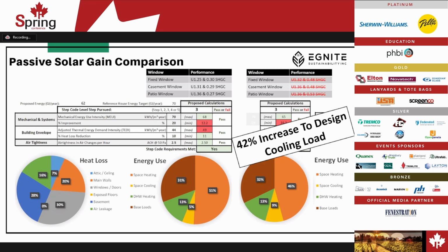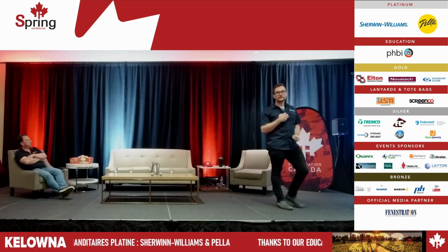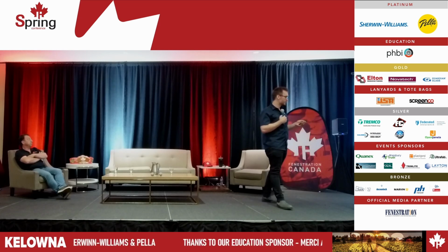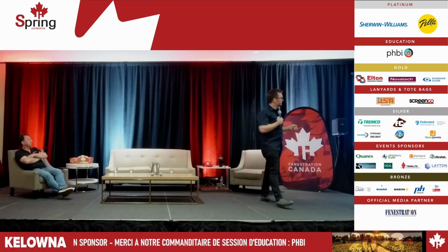And in some cases, if our mechanical contractor hasn't done the heat loss according to this higher solar heat gain, they're not going to be meeting the set point temperatures to make sure that house is comfortable too. So it's pretty high risk when we're not going through integrated design and people aren't speccing the right equipment across all the different disciplines. We can have some pretty unhappy clients and homeowners as well.